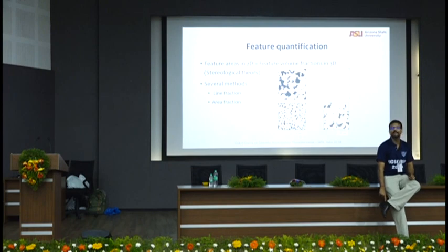That's why sample size is important. Standard deviations are important. You can't say, I don't like that sample. If you have a real reason not to like that sample, when you know that you made that sample poorly, it's not correct, yes, ignore it. But you can't randomly ignore. Yeah, I tested the strength. I was expecting 45. I got only 35. Therefore, I removed it. You can't pick and choose like that. That is not the right way of doing research.